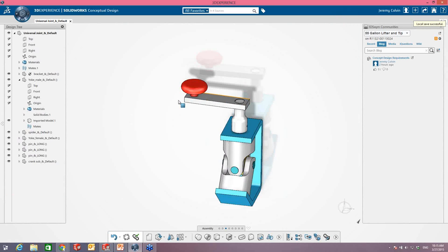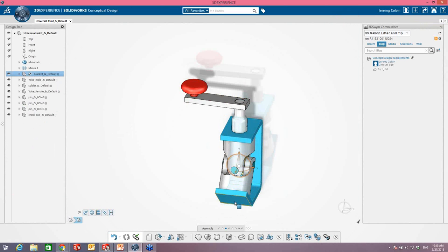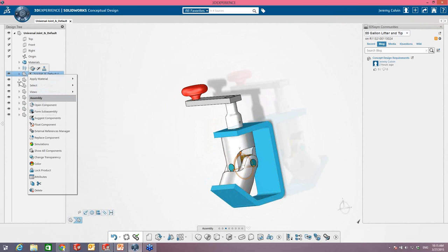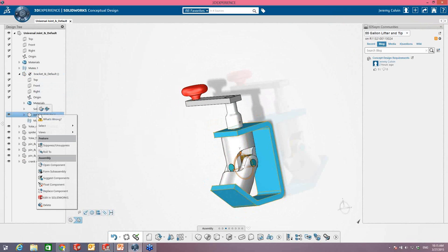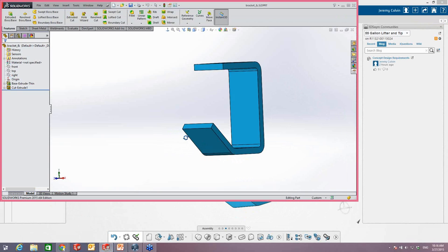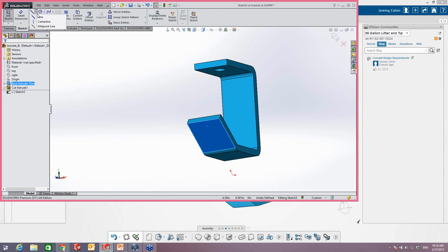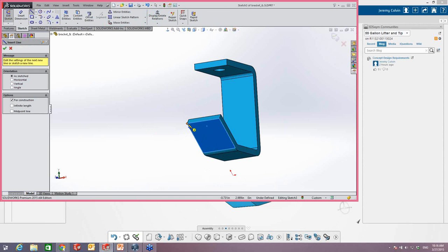So the benefit of this, I suppose, just to give you a full demonstration, is say we want to put a hole here in this plate in the bracket. We can pretty easily open that in SolidWorks, again going to our imported model. And being back in SolidWorks, we can quickly open a new sketch, just go ahead and draw a center line across here.